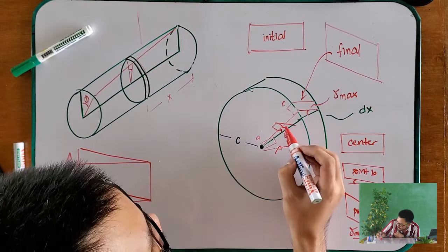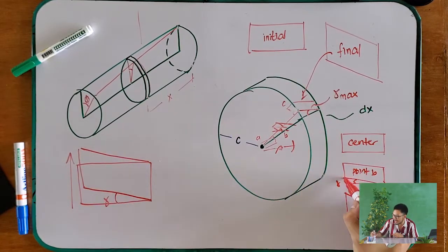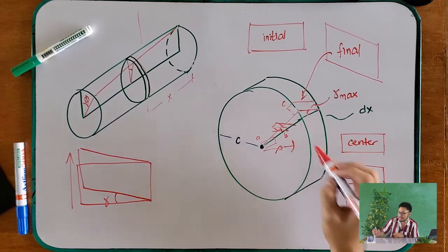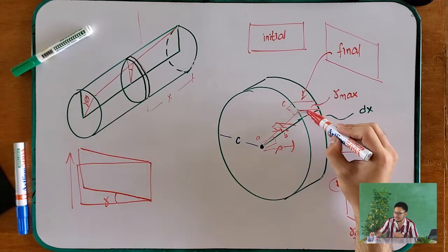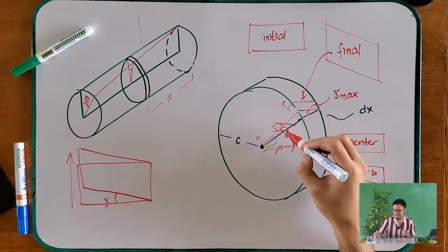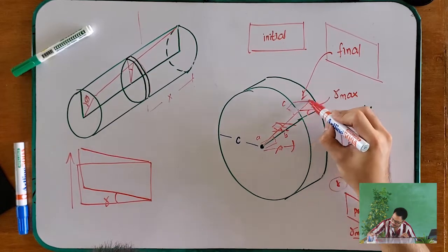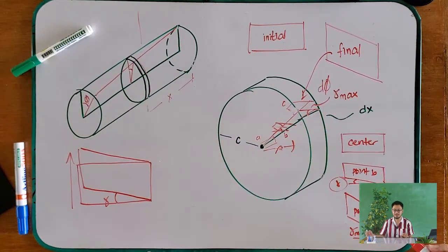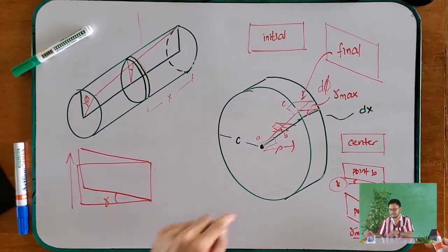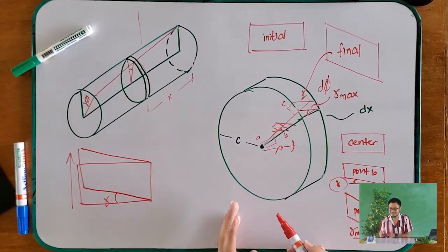And your shear strain at rho is your gamma. For this application, from one side toward here, it makes an angle, and that angle is what you call d phi, your differential angle of twist, along this plate element.